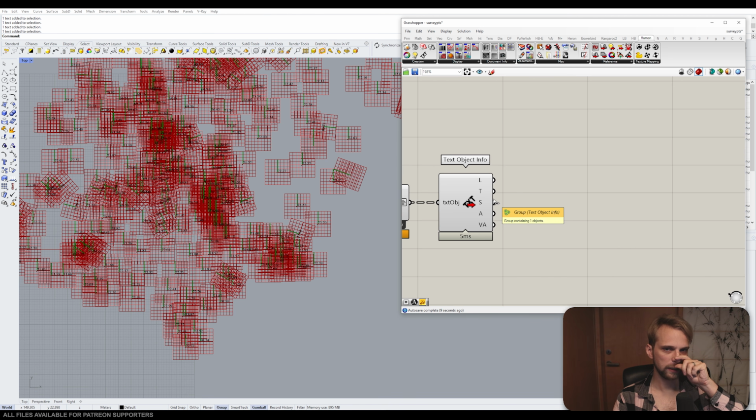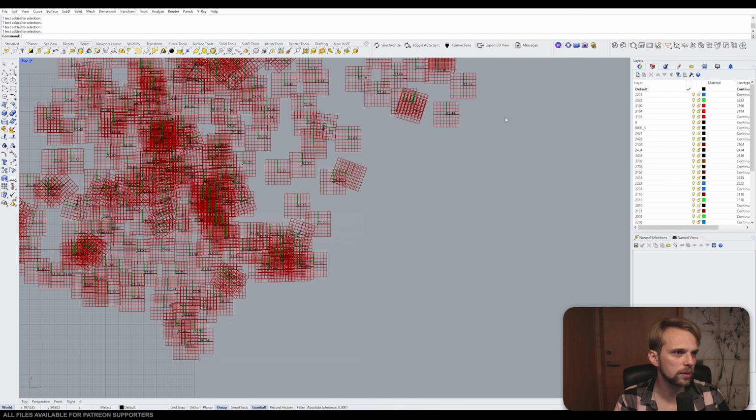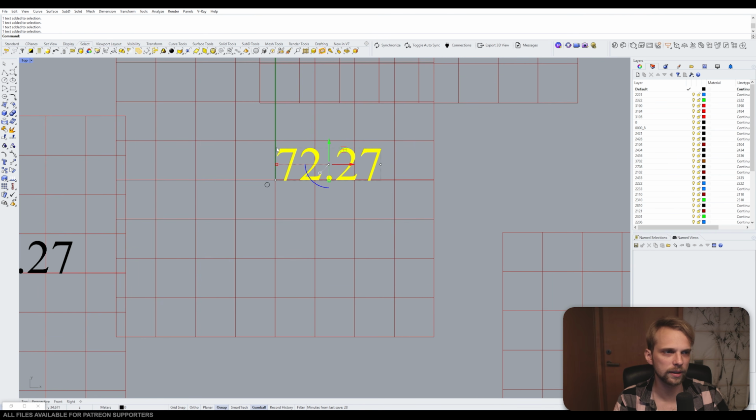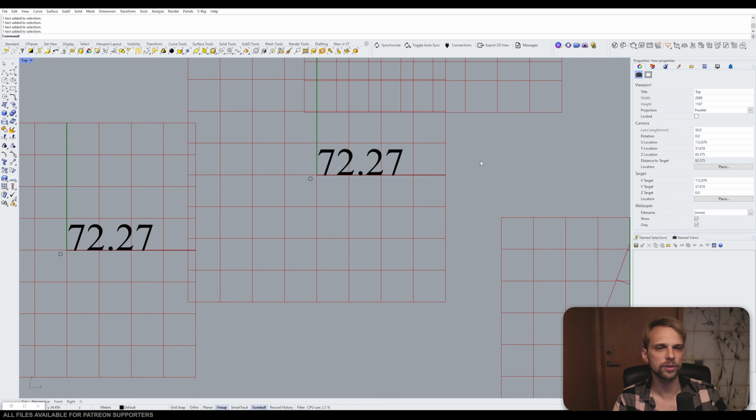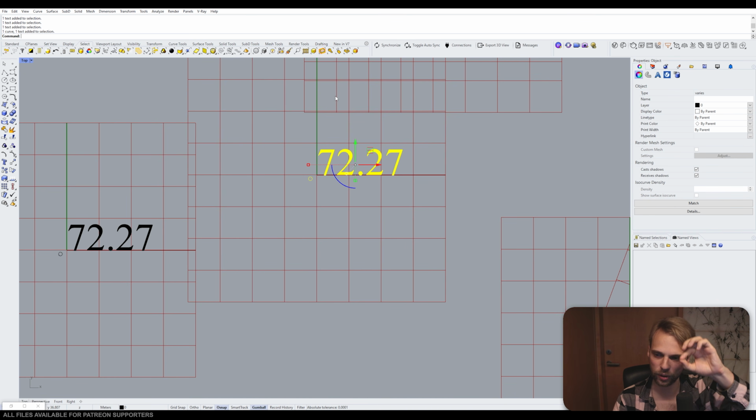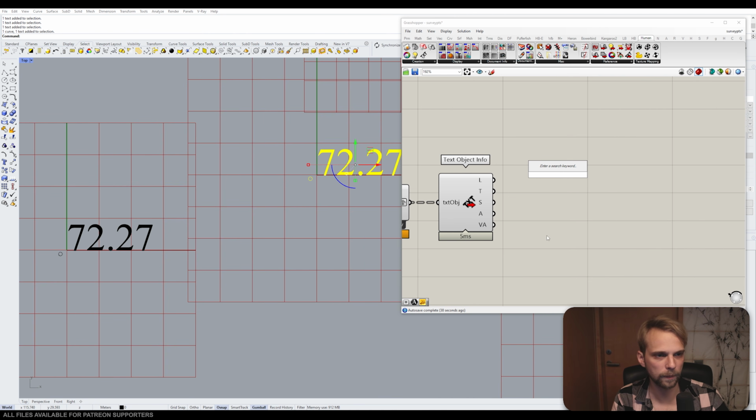So the first thing is eliminating all of the text that is not size 2, if I remember. I'll select this text right here, go to properties, size, height 2. Any text that is not height 2 is not going to be the height point measurement text, so we just get rid of it. So for the size, I'll ask a question of equality, 2.